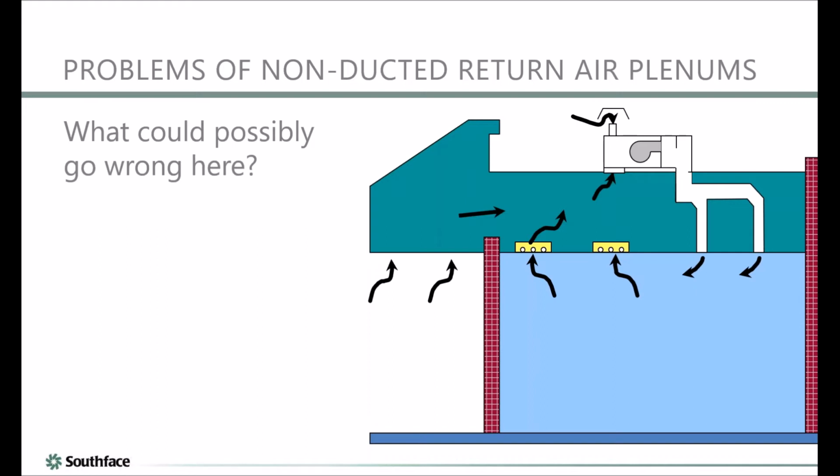There were probably some openings to allow air to get back up there, but the challenge was that the exterior wall, and also this interior wall that went to another space, did not seal to the top when you pushed the drop ceiling tile aside and looked out. In other words, you really didn't have a plenum.